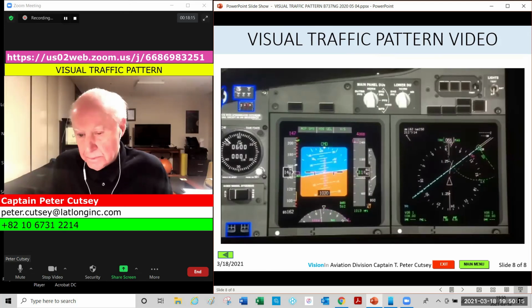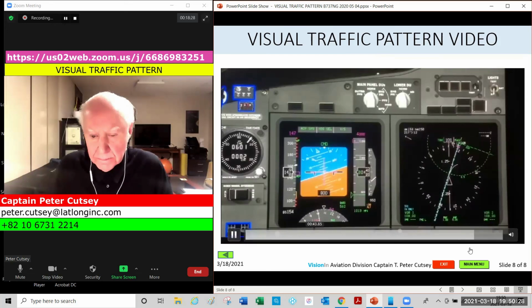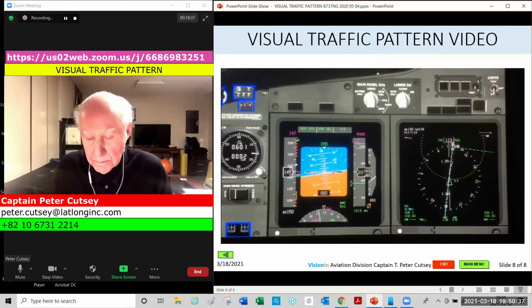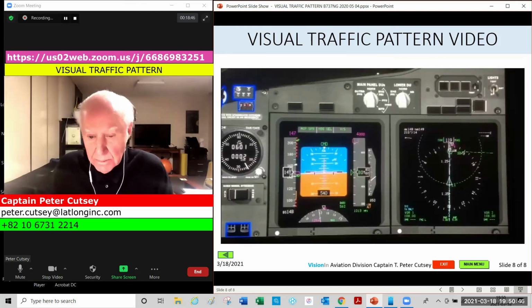Making a small correction. And here we are coming up to the 700-foot mark, and we are approximately 2.5 nautical miles. We're going to track the center line, and today it'll be a heading of 125. We're visual anyhow, but a heading of 125 should keep us on the center line, as you can see. Plus 100. Continue. Minimum.